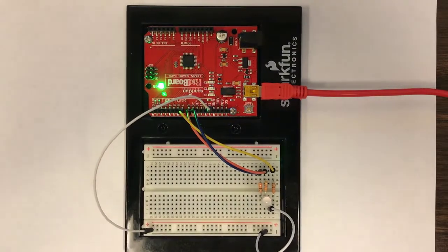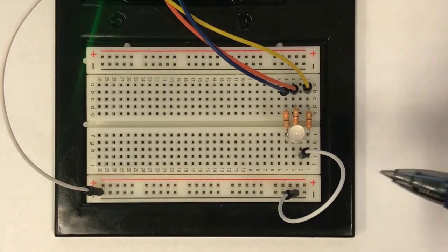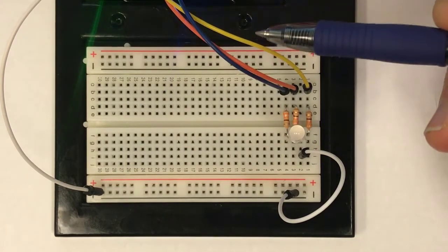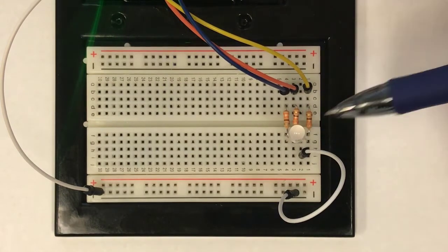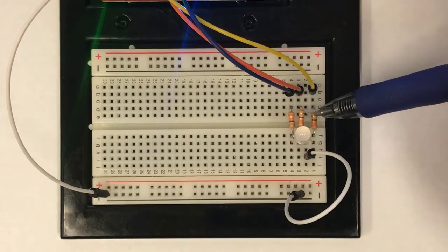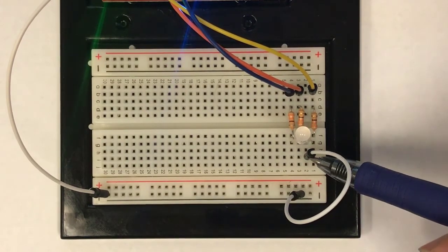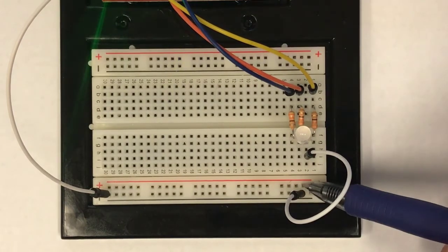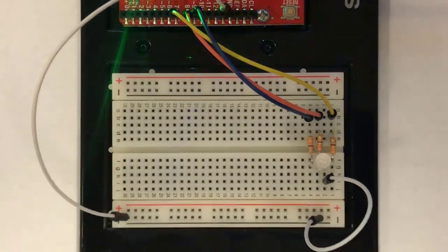Now I've already attached those 4 terminals to this board, and so we can see how the board is connected. In this circuit, we have the 3 wires coming from the Arduino. Those are connected to the R, the G, and the B. Here you can see this is the RGB LED. We have 3 resistors. These are the current limiting resistors. Those are very important. Don't forget those. 330 ohms for each one of them. Notice that it's not going to this terminal because that's the longest one. That's the ground terminal. And instead of having a resistor attached to it, that's going through this wire to the ground connection of the board. And then, of course, over here we see that that ground connection is actually attached to the ground connection of the Arduino.